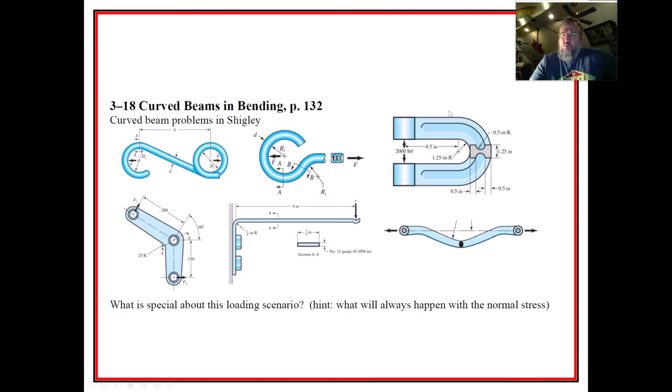So let's take a look at one of these and try to see what I'm talking about. You see that this load on this piece is 2,000 pounds going up on this part and down on this part. Well, that's going to tend to try to bend this section, but also just the act of it being there will cause an axial. The way to really understand this is to draw a free body diagram of it through this section, and you can see that it's going to have not only the bending, but also the axial. The same thing is true with this strut.